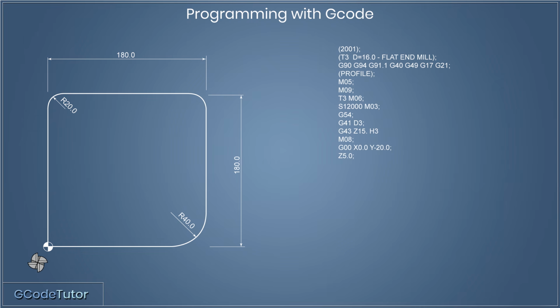Now as we move the cutter around under our rapid travel command G00, it's still at its tool change height, its highest maximum Z height permissible. So we're going to rapid this down to 5 millimeters above the job. Now G00 is still active, so we'll do this at the fastest feed rate possible. I'm rapiding down to this point and not into the material because we can't remove material when we're using G00. It would move too quickly and possibly break the tool.